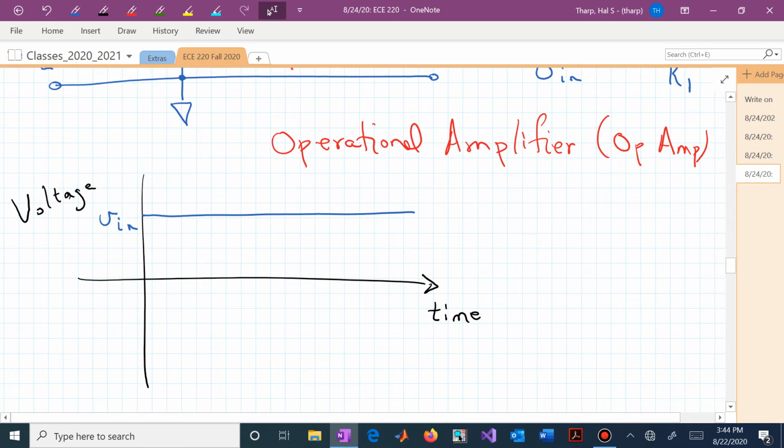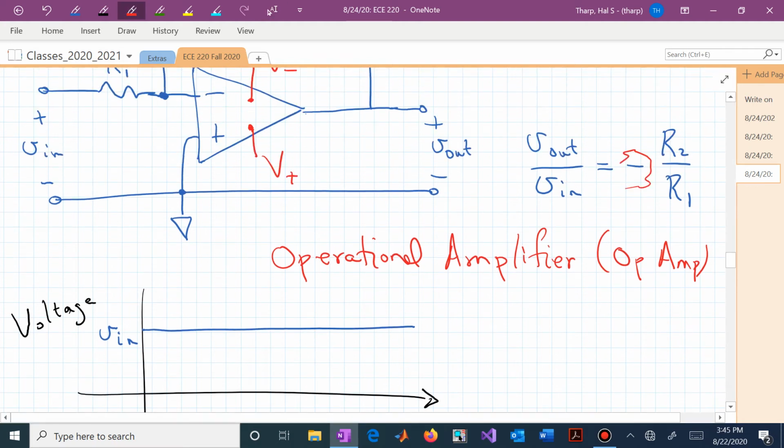In the previous chapters with just purely resistive circuits, we were able to scale them down, but now with this operational amplifier, if we choose R sub 2 and R sub 1 appropriately, maybe we can scale it up in magnitude. Obviously it's going to have a negated value from the input voltage. That's a result of this inversion or negative sign in front of this operation of scaling the signal.